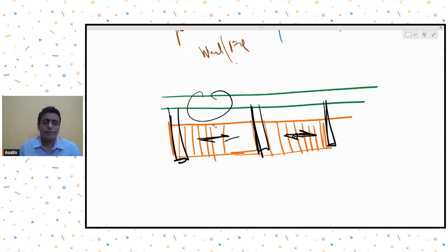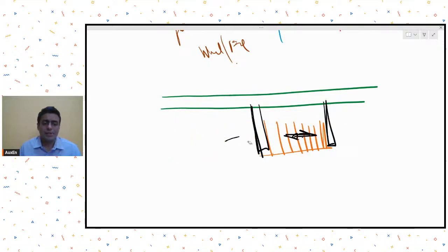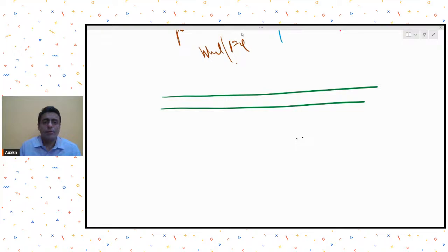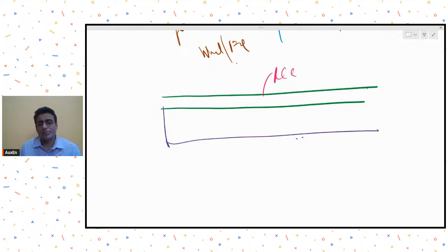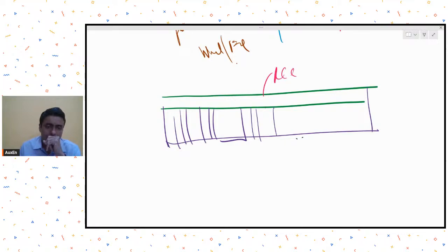If you have taken the entire system cantilevering out, maybe let's say you had an RCC wall over here, in such a case, you can take the entire system cantilevering out from the RCC wall itself. In this type of situation, your staircase will be a transversely supported staircase spanning like this. So whatever your system is, accordingly you will have to design.